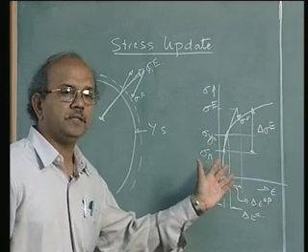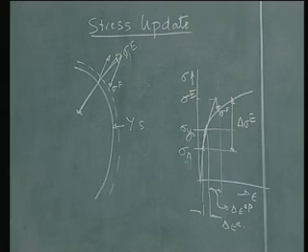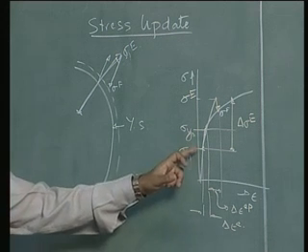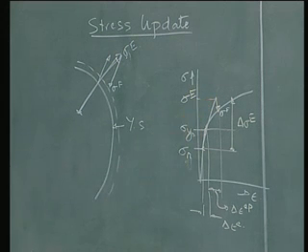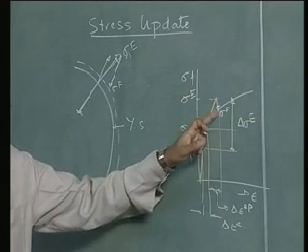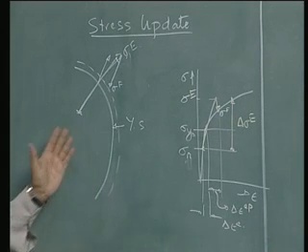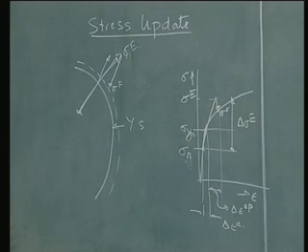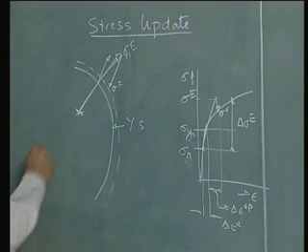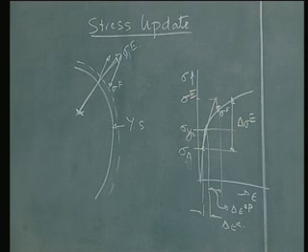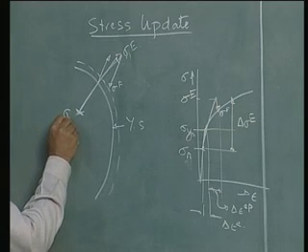And in fact, we had seen this type of algorithm when we were doing the one-dimensional case. Remember that we had predicted using the elastic properties. In other words, there is an elastic predictor followed by a plastic corrector. The game that we are going to follow in this case is exactly going to be the same with, for example, starting from this point. We had called that sigma n last time. Since it is going to be inside an iterative loop, let me call that sigma x.